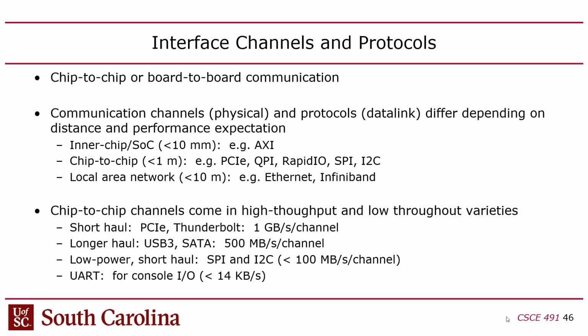But in this class, we're looking at options that are lightweight, low power, and relatively low performance. Specifically SPI and I2C. Some of you have probably heard of those already. Those are the protocols that you use whenever you do Arduino type stuff, and they're very, very popular. I2C is used even in heavier weight systems. If you use HDMI, and maybe even DisplayPort, although I don't know that one for sure, when you connect your monitor to your computer, there's a communication that goes backwards from the monitor back to your computer, right?